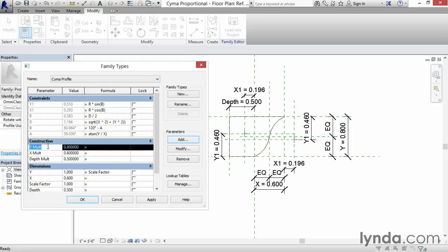So I'm going to come over here and select y_mult, do Control-C on that. I want to multiply it times y_mult. When I do that, it will gray out y. It's no longer editable, and it will make it 0.8. So it's right back to being the same size that it was a moment ago, but it's ultimately being driven by these 2 parameters, scale factor and the y_mult.